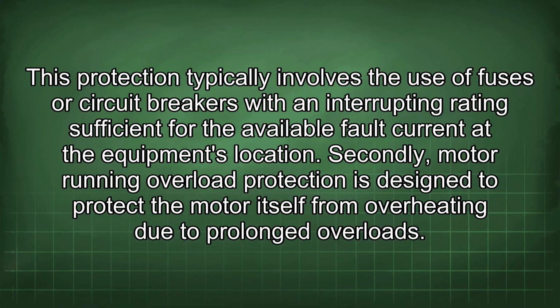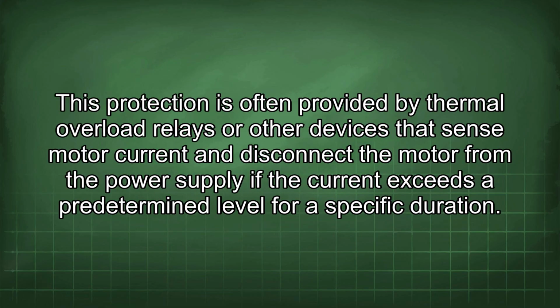Secondly, motor running overload protection is designed to protect the motor itself from overheating due to prolonged overloads. This protection is often provided by thermal overload relays or other devices that sense motor current and disconnect the motor from the power supply if the current exceeds a predetermined level for a specific duration.